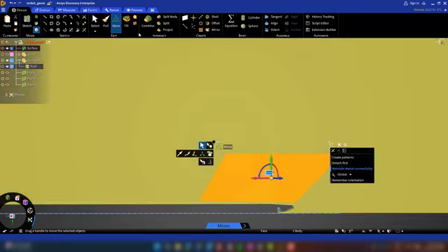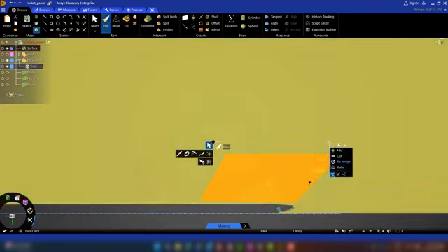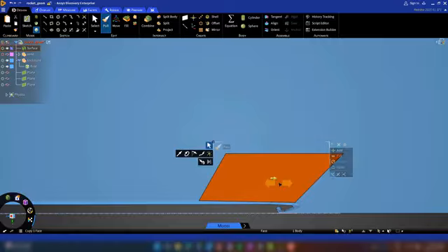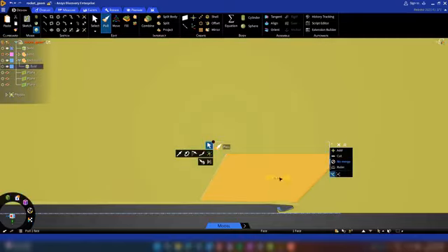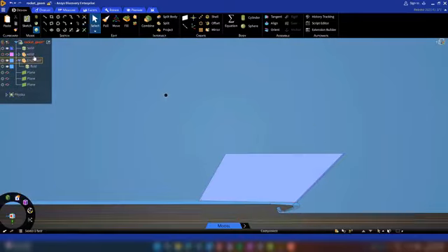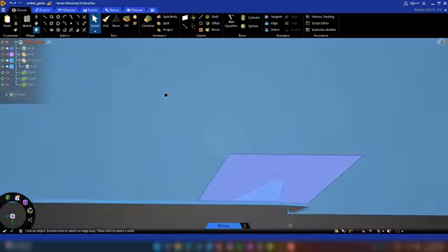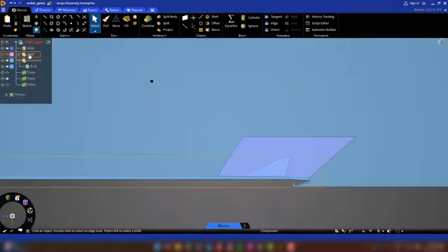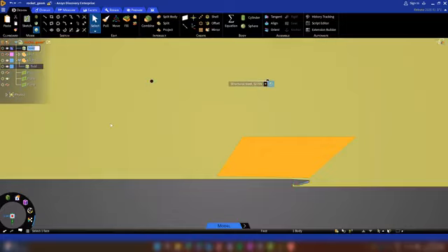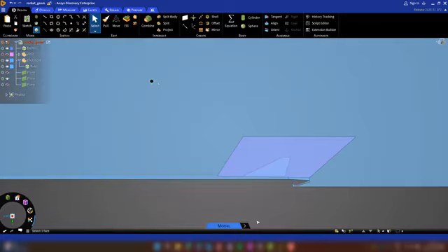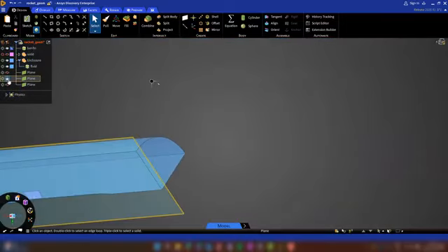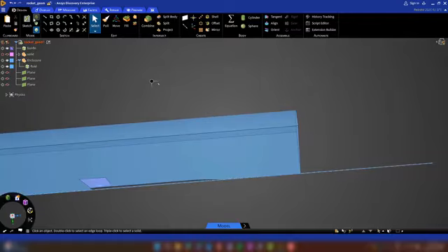When pulling this surface, ensure that no merge is selected so that a separate body is created from the extrusion. The overlapping objects must be in separate components in the object tree, and the body of influence, named BOI, for proper selection and local sizing controls in Fluent meshing.